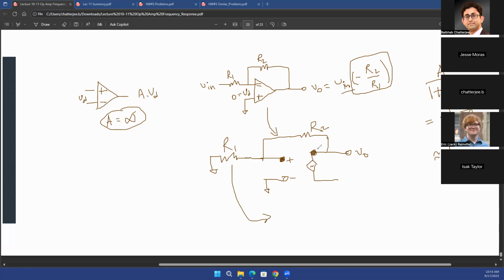That voltage is going to be a voltage division ratio. So you start from this point, traverse your way back toward the input, right? So what is the voltage at this point? The voltage at the positive terminal or the inverting, let's say this particular node, is going to be R1 divided by R1 plus R2.